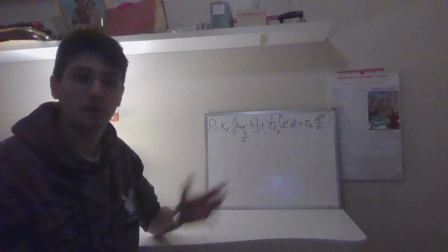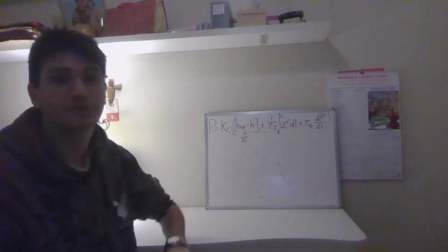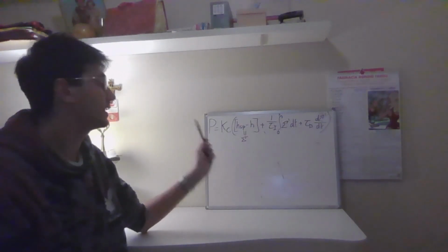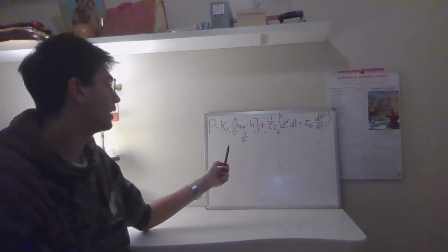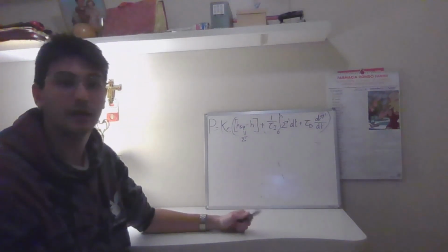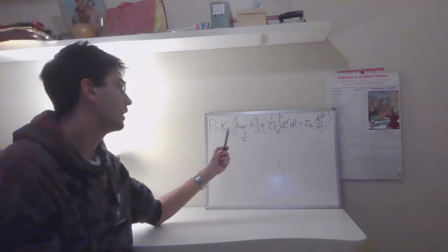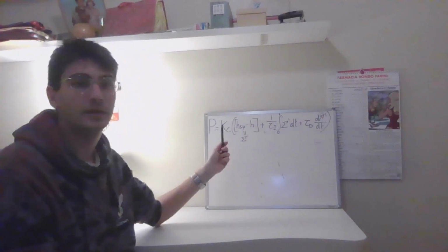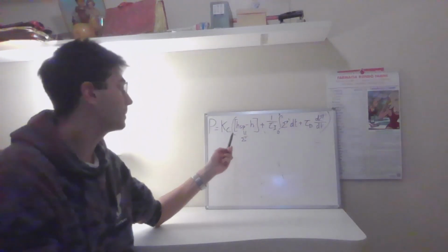So hello, and welcome back to the whiteboard. I've gone ahead and written down our expression for our PID controller up ahead. So it's simply KC, which is our proportionality constant, multiplied by the error. In this case, we are dealing with the height of two tanks. So it's simply the set point height minus the actual height of the reading.